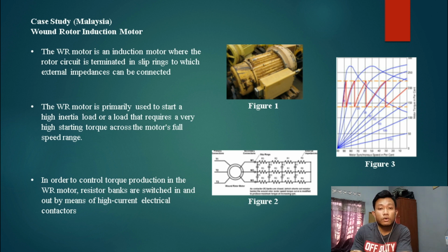The reason why I chose the wound rotor induction motor is to compare retrofitting smaller horsepower, which is 500 horsepower or below, vintage wound rotor motors with a modern low voltage induction motor and variable frequency drive, which is VFD, functional equivalent.